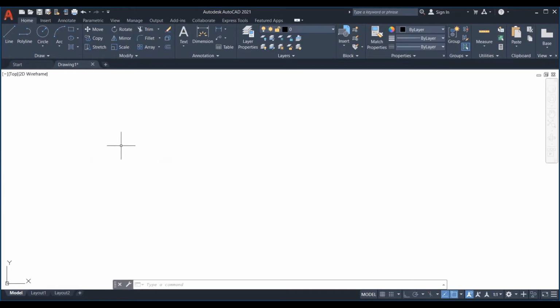To modify an existing drawing template file, click Open, specify Drawing Template .dwt in the Select File dialog box and choose the drawing template file. Important: if your company has already established a set of drawing template files, check with your CAD manager before modifying any of them.